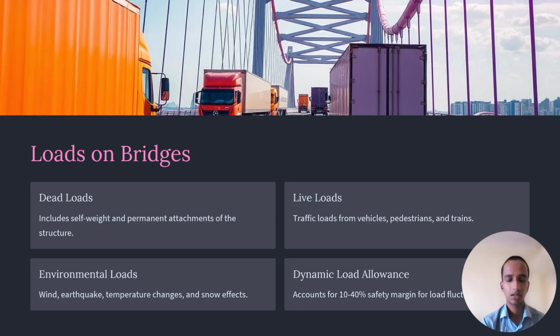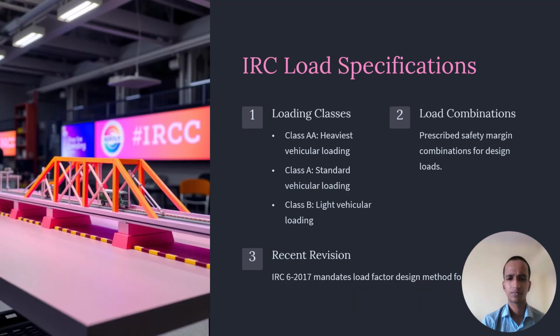In places where seismic activity is more, the earthquake chances are more. So one needs to keep this in mind and also refer to the seismic zoning available in the IS standards. And generally 10 to 40% of factor of safety is provided to the loads.